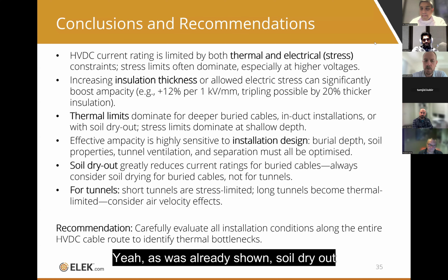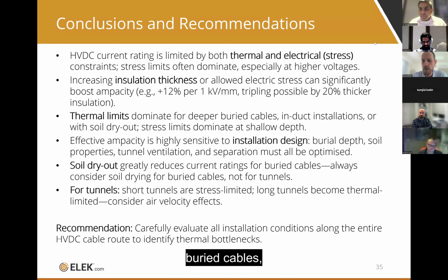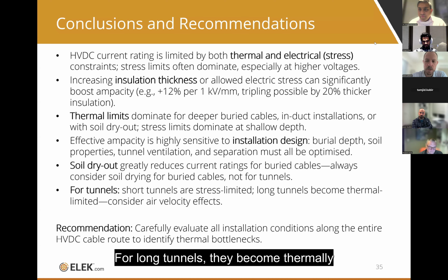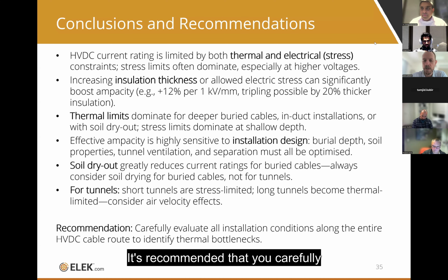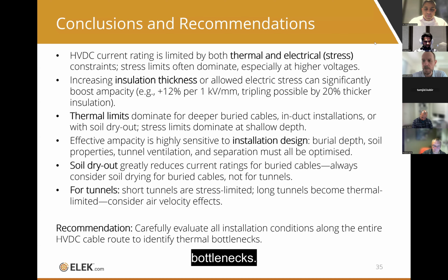As was already shown, soil dryout greatly reduces current ratings for buried cables. You should always consider soil drying for buried cables, not necessarily for tunnels. For short tunnels, cables are usually stress limited. For long tunnels, they become thermally limited, and you should consider the air velocity effects, which could have a significant impact. It's recommended that you carefully evaluate all installation conditions along the entire HVDC cable route to identify thermal bottlenecks.